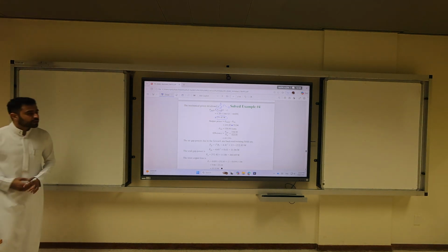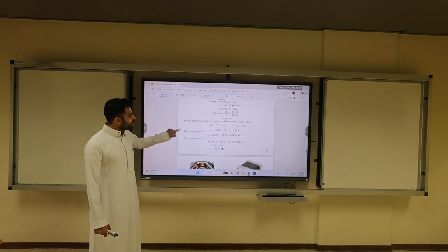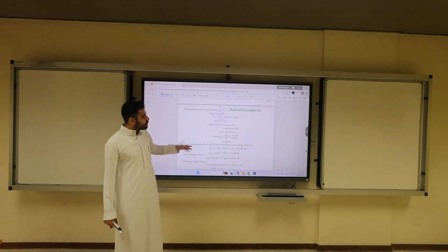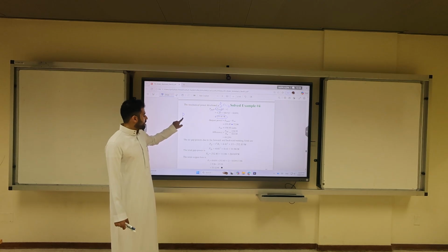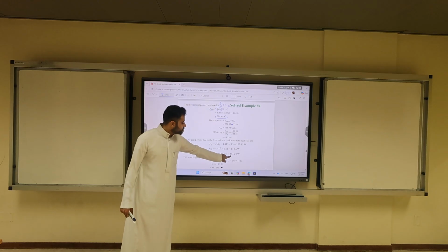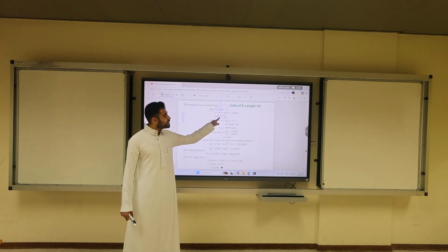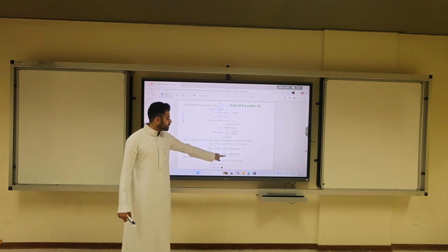So let's continue. Now he asked about the air gap power. One way to calculate the air gap power is you get this PG multiplied. What is the air gap power? It is 264.69, which is higher than this number. So you can get it by just getting these two numbers, 188.5 times 1.28.